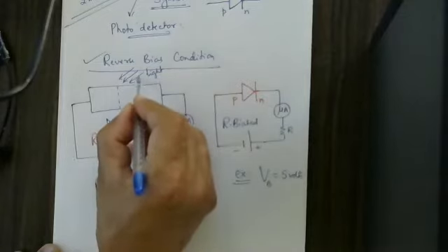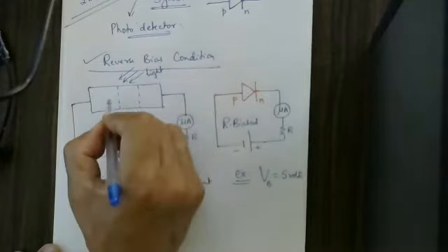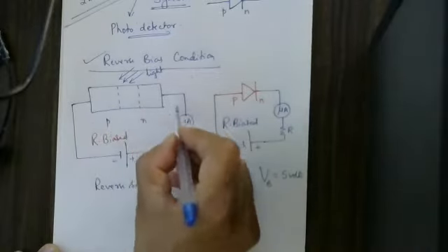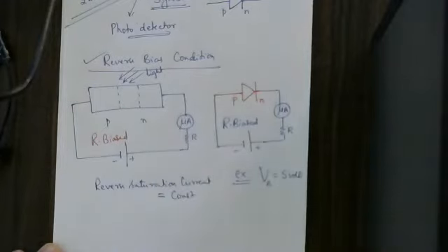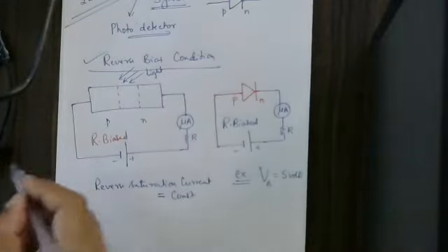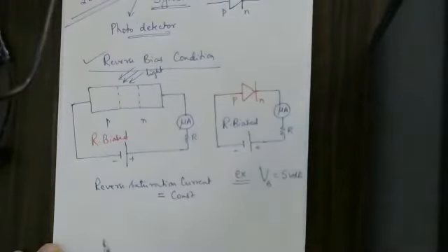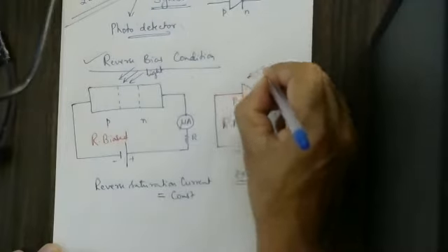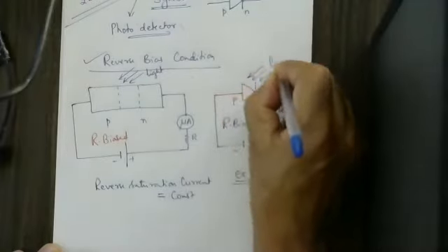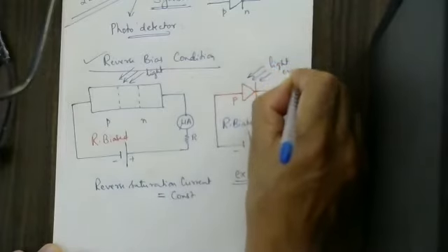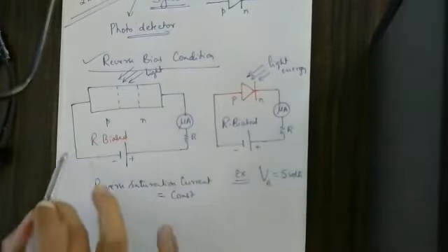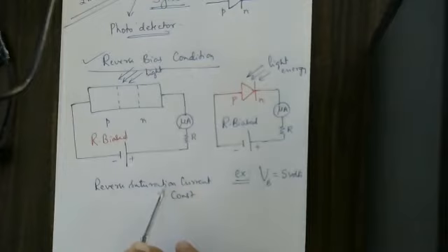then this particular light energy produces a larger amount of electron-hole pairs here, and hence the reverse saturation current suddenly increases. Therefore, it starts to conduct here because the current flow suddenly increases. That's why we are supposed to write the light energy here. This is light energy of a suitable energy that we are supposed to put. Then only does the current start to flow as a larger quantity, not this constant value. Suddenly the current strength increases.